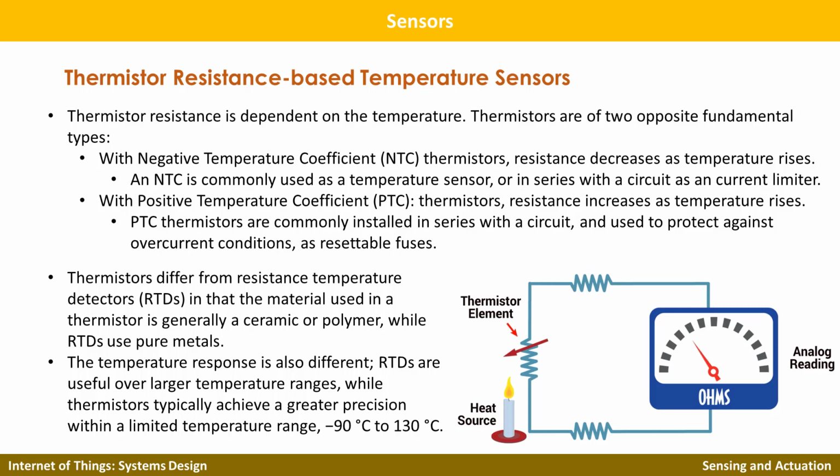There are a number of advantages and disadvantages in thermocouple sensors. The advantages are that they are simple, rugged, inexpensive, self-powered, and have a wide temperature range. The disadvantages are that they are non-linear, low voltage, have a reference requirement, and are the least stable and the least sensitive. So if you are looking for a simple, rugged, inexpensive solution with a wide temperature range, a thermocouple is your best option.